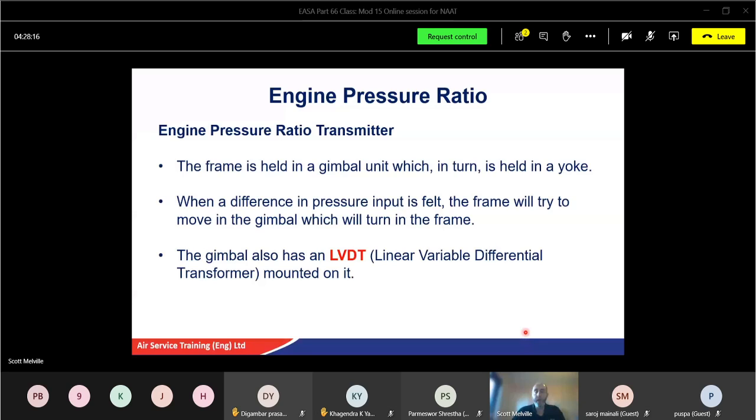Typical setup for checking oil pressure. This explains a diaphragm spring type sensor. In this case, we've got a spring sensor which is keeping the contacts away. We've got oil pressure in here. As long as the oil pressure is sufficient, the spring will keep it away, but if oil pressure drops, the spring will push down to a contact and indicate low oil pressure. So providing the oil pressure is high enough, it will keep this contact away from the bottom contact, just by pushing it up out of the way. Nice and simple. But as soon as you lose oil pressure, the spring takes over, pushes that contact down onto this one, and that will make a signal saying we don't have any oil pressure or low oil pressure.